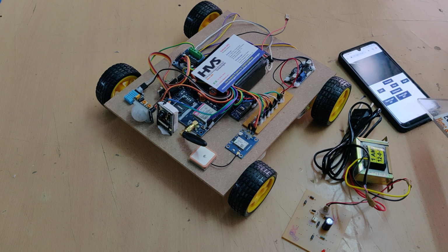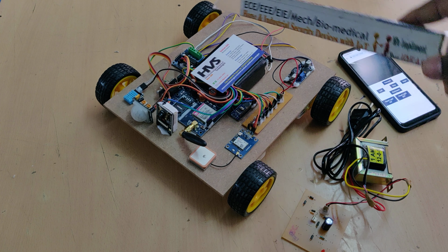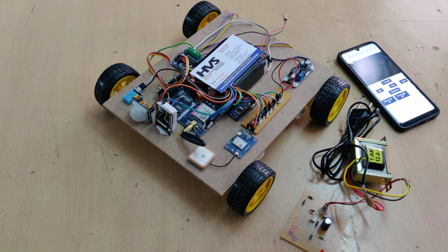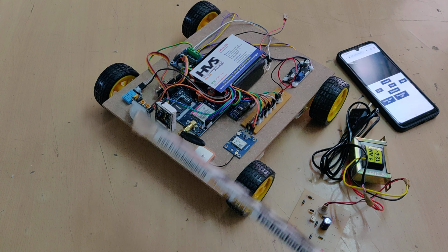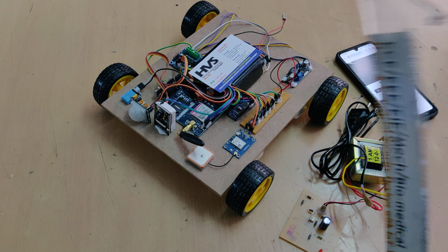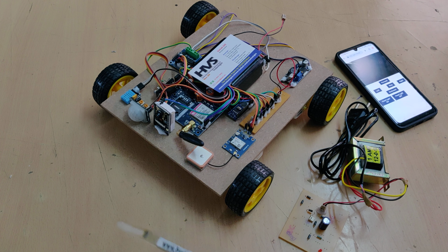Directly it will take the input from the browser and control the robot with the help of this L293D motor driver. The connection between these two is pin numbers 10, 11, 12, 13, which are connected to the ESP32 camera. The headlight is directly interfaced on board; there is an LED on this ESP32 camera.